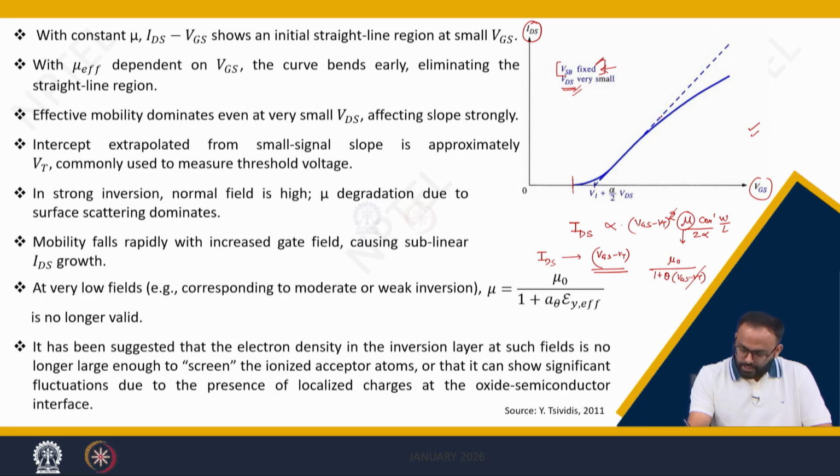You can see this linear curve when you plot the characteristic, after the threshold voltage, where the transistor is entering from saturation to linear. This is not a very stringent criterion, just to show you that the current will be linear. After this part, the triode region starts.